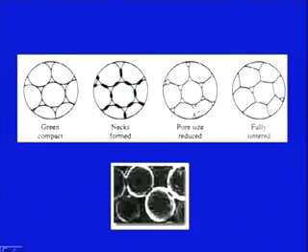This has been explained with the help of another diagram. Here we can see a green compact, with all the spherical balls shown. Inside we can see there are certain voids, present in between the spherical metal particles. When we subject this green compact to the sintering temperature, neck formation takes place wherever two metal particles meet.